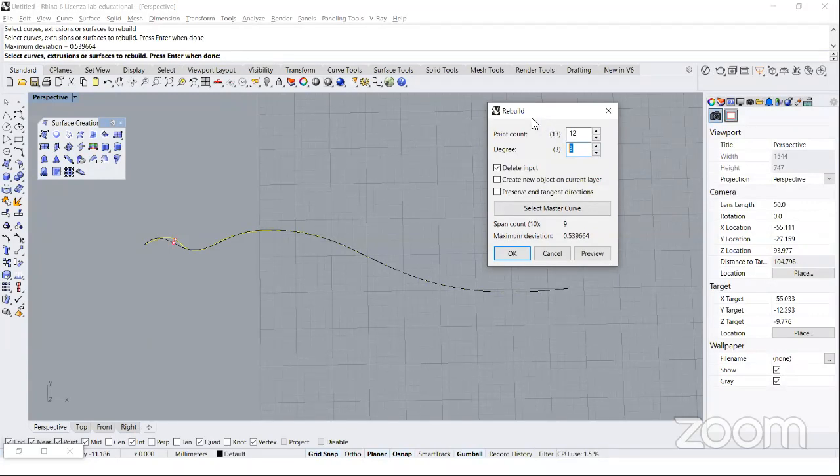It is saying that if you have 13 control points, you have 10 spans. 10 spans means that your curve is divided into 10 segments, so you have 11 knots. Each knot corresponds to one endpoint of each span. One knot corresponds to the start point, and one knot corresponds to the end point.